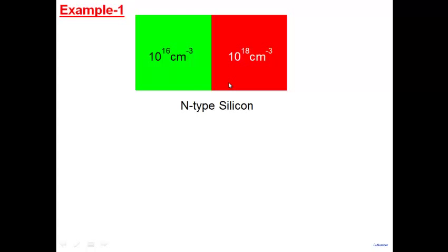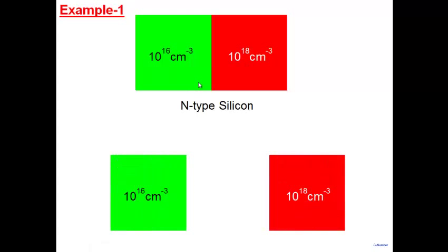All right. So the steps are, just follow these steps, the same steps we do for all semiconductor devices. We just repeat them. Note that the two semiconductors are in contact, so they are in thermal equilibrium. First, I imagine them to be isolated. So separate them out. This has two distinct parts. Separate those two distinct parts here. So now they are isolated. They're no longer in thermal equilibrium.